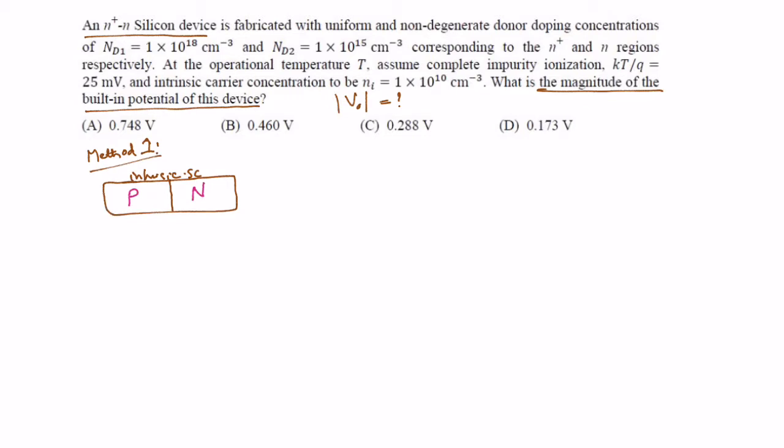Before doping, if you only consider the intrinsic semiconductor, every semiconductor will have holes and electrons, all at the same energy levels. But whenever one half is doped with trivalent and the other half with pentavalent impurities, the electrons and holes in the p type will not be at the same energy level as the electrons and holes of the n side.